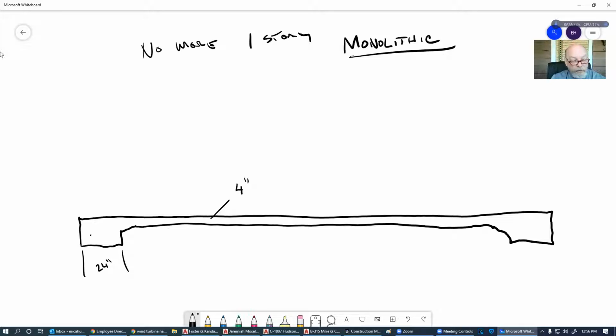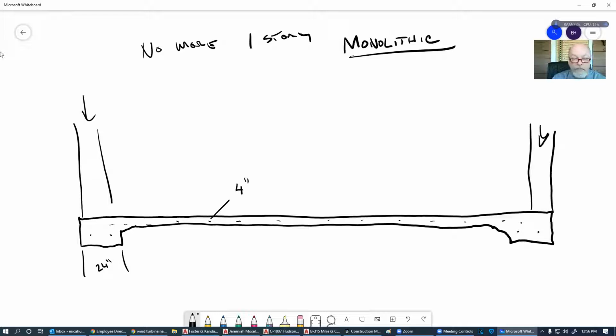You're still going to be required to put rebar in. We're going to talk about that rebar in a minute. And you're going to be required to put in metal reinforcement through there. But again, we're not putting a 2-story house with a basement on it. So we've got just minimal weight forces coming down on this thing. And hopefully, if we've built this with the right amount of reinforcement, the whole thing's not going to settle at one time.